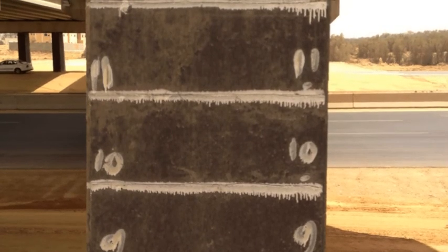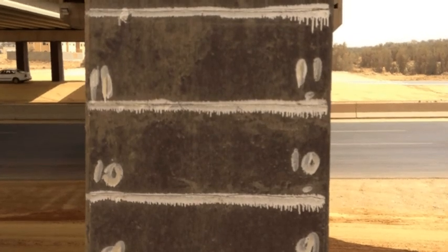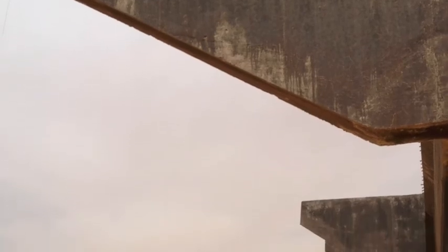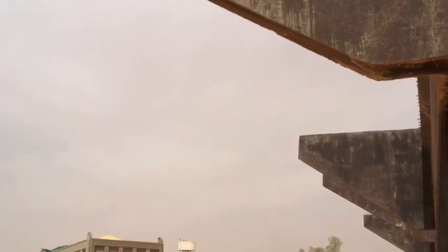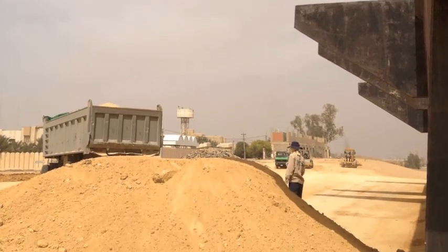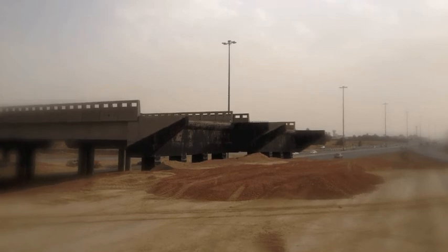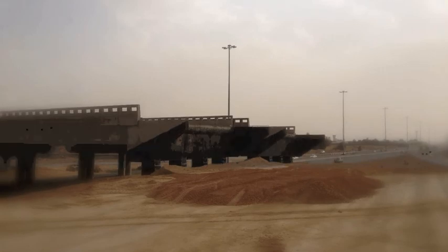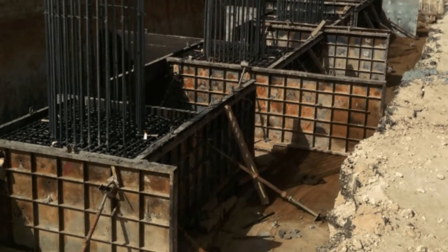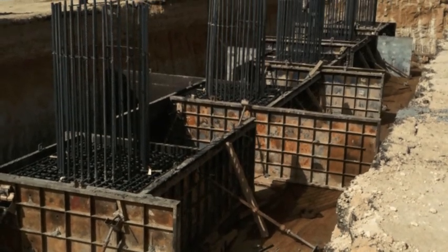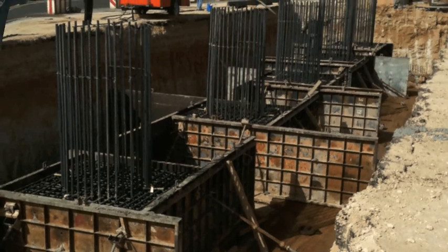The substructure is basically designed in accordance with the technical requirements and the construction methodology. The excavation required for a foundation may need to exceed a sizable depth, involving hard ground. Before the soil and rock are reachable, engineering measures will be involved to avoid water and prevent a collapse of the excavation. Piers are the vertical structures that support the ends of a multi-span superstructure at locations between abutments.